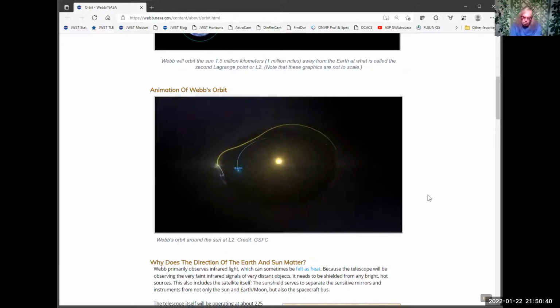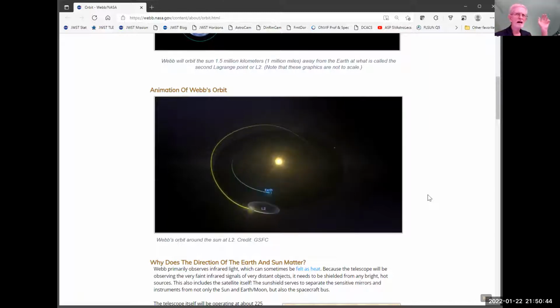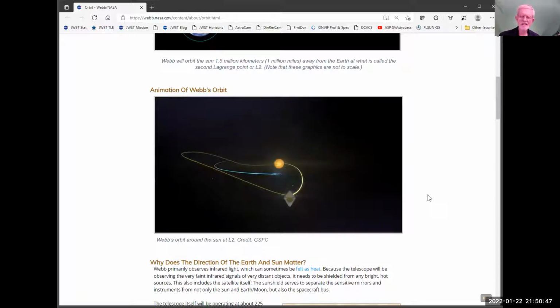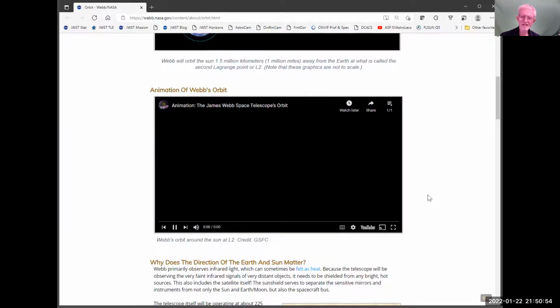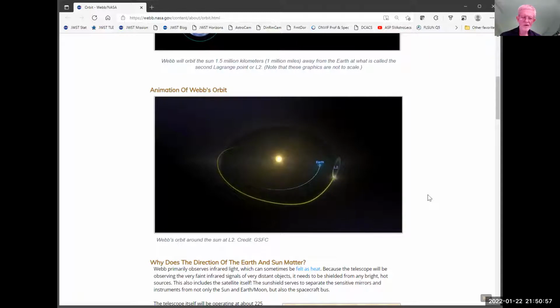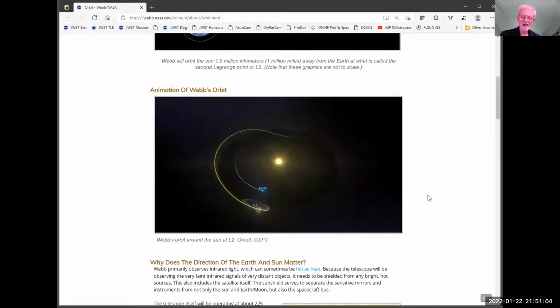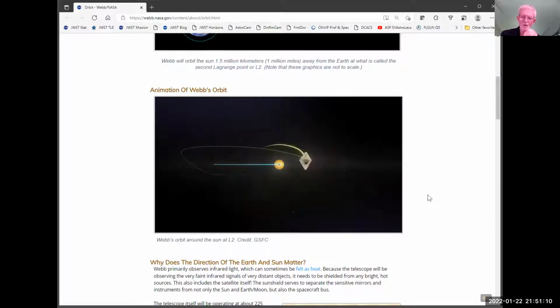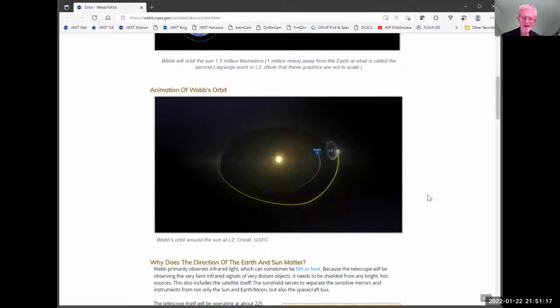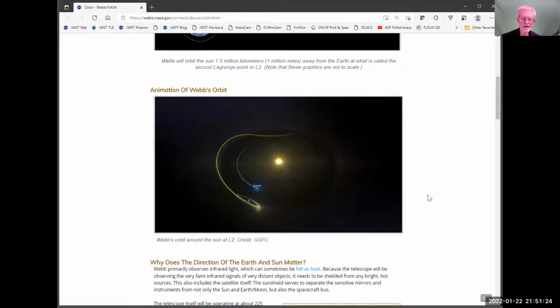Yeah, that too. Although I think it was about 12 years ago, they found the reason why momentum wheels were wearing out so fast. Turns out it had to do with the materials and the creation of an electromagnetic flux between the bearing components. So it would literally pull the shaft more in one direction magnetically, which would cause it to wear more there than on the other part of the shaft, which caused it to wear the bearings out. And they did a little chemistry, a little metallurgy, and changed the metals that they used in the outer shell of the momentum wheel bearings, and now they should be good for much longer.